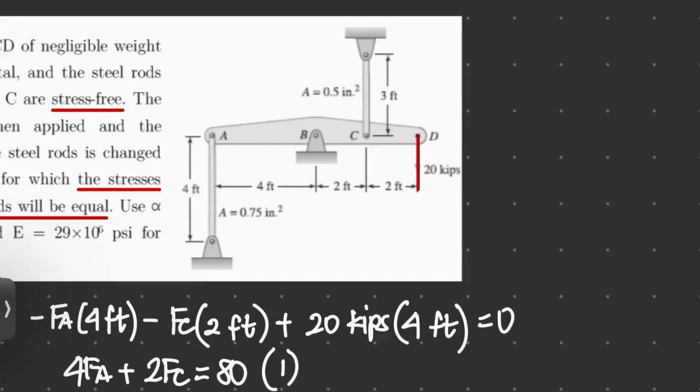If it moves down, and we know that there's a support here, the support hinders movement up to this point. So let's draw a straight line. Then, since it hinders movement here, we know that there should be an upward movement or rotation at point B. Therefore, there would be an upward deformation or deflection at point A.